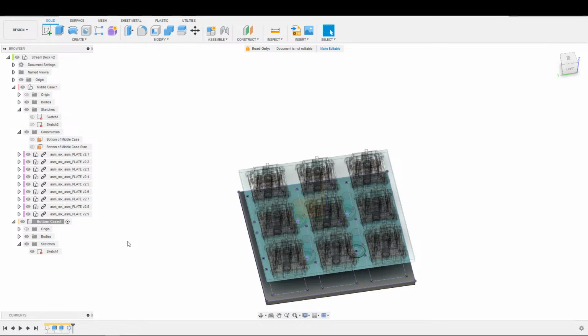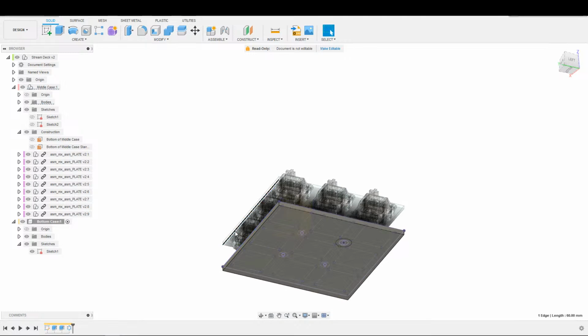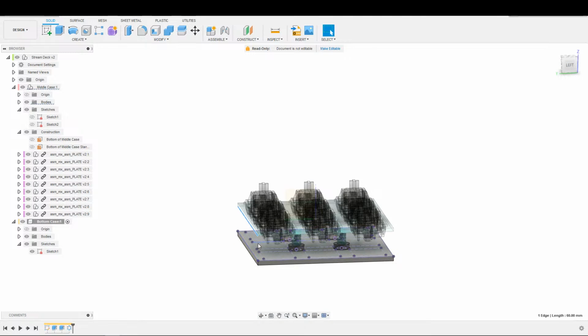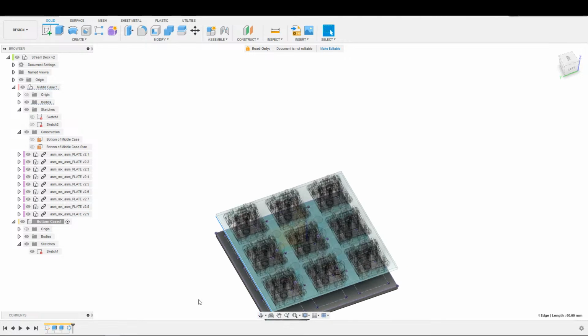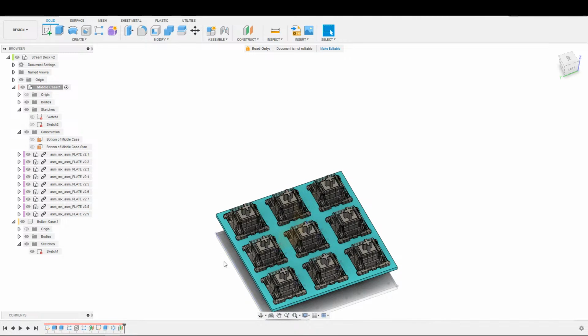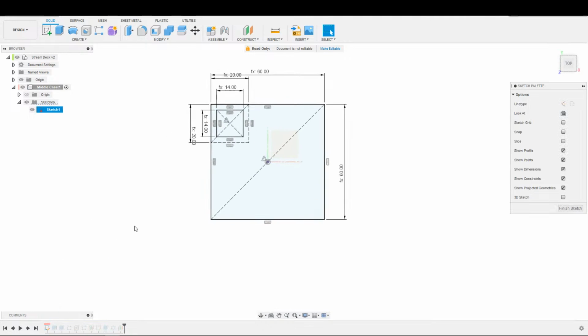I like the idea of having a clamshell-shaped Stream Deck, rather, not Steam Deck. That's a completely different thing. Stream Deck case. I like the clamshell look where it flares out in the middle and then narrows at the top and bottom slightly. That just is appealing to me. But because we're going to be putting the slides or rollers on the sides here, it really behooves us to have a flat edge. So I was going to leave this as it is, and then extend this out and loft this wall up to meet the top one. That was my plan. But at this point, because we're going to put the rollers in, I guess I will roll back and just make the middle case bigger, and that will make the bottom bigger in proportion and give us flat walls on the sides afterwards. So let's do that.